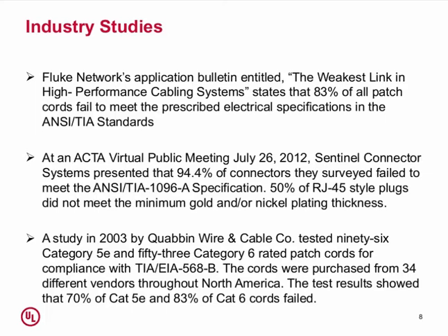ACTA, back in 2012, had a presentation done by Sentinel Connectors, and they found, in some work that they did, that almost 95% of the connectors they surveyed didn't meet the 1096A specification, and 50% didn't even meet the gold thickness or nickel plating thicknesses as required by that specification.